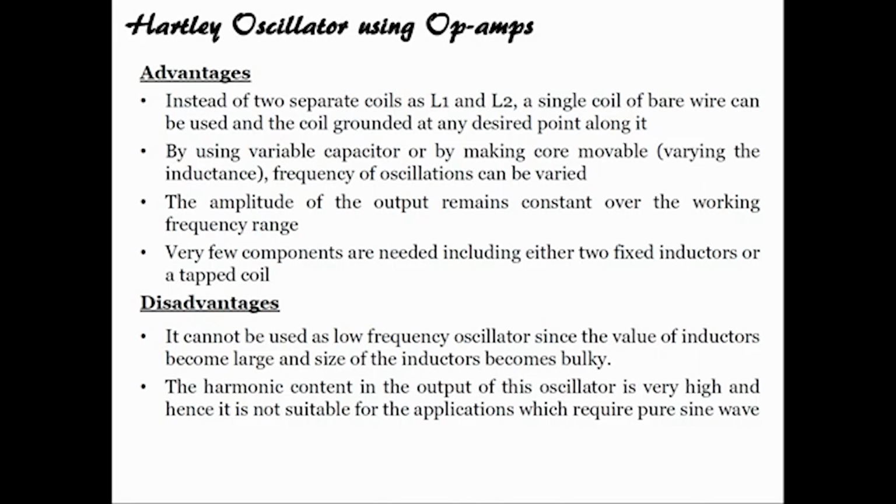But there are a few limitations. It cannot be used for low frequency oscillation, since the value of inductors becomes large and the size of the inductor becomes bulky, which is obvious. The harmonic content in the output of this oscillator is very high, and hence it is not suitable for applications which require a pure sine wave. So, the harmonic oscillations limit its use for pure sine wave.